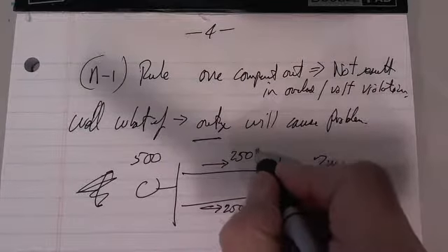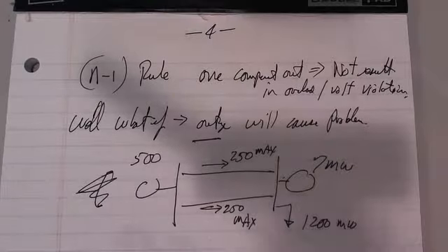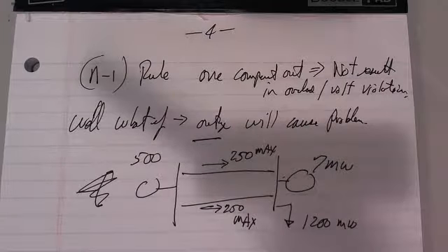So this is max. Now, what determines the maximum power carrying capability of a transmission line? It is probably the transformers at either end, unless there are no transformers, in which case it's just the wire. And on a hot day, how hot is that wire going to become?